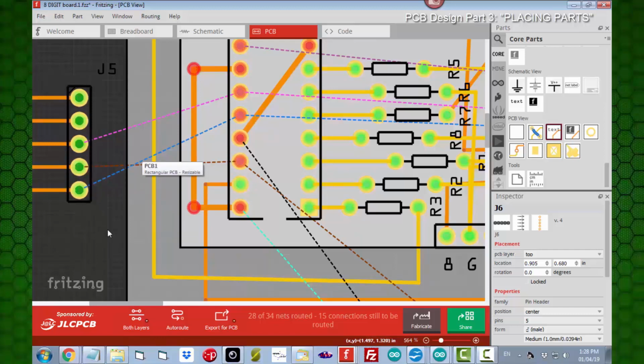I think we might want to just change the order in which these leads are connected. We can do it here. It's just that when I did it on the breadboard, I didn't see how this was going to be a cross when we came to the printed circuit board. And it doesn't have to, because we can connect these 5 pins up here to our IC in any order we want, as long as we pay attention to what we're doing.